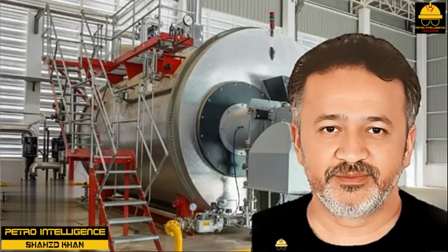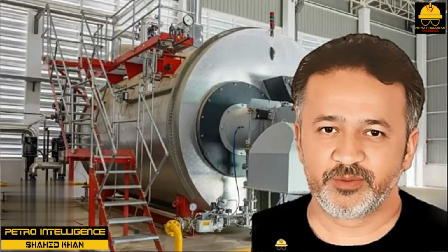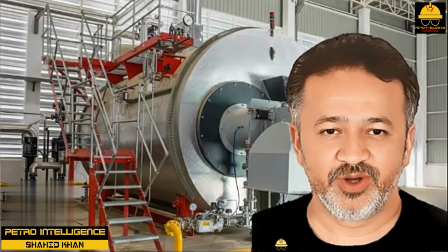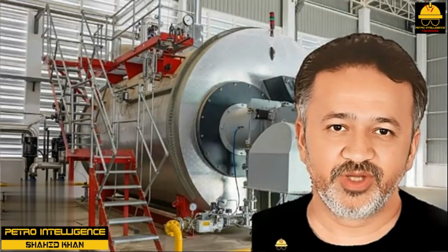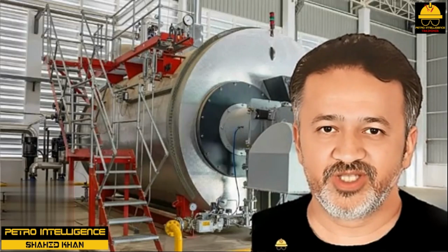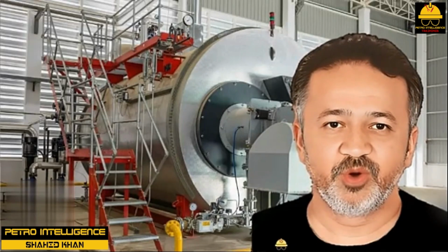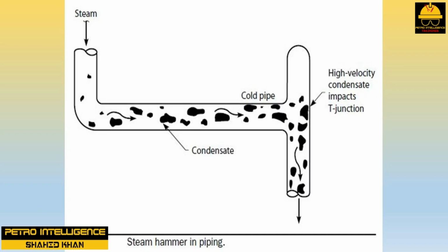Water hammer. Steam or water hammer, more properly called hydraulic hammer, is one process plant phenomenon familiar to the general public. When trying to warm up the steam system of a large amine plant in your plant, you can hear the crescendo of crashes due to steam hammer. The cause of steam hammer is illustrated in this picture. In general, hydraulic hammer is caused by the sudden conversion of the velocity of a liquid into pressure, causing a surge of pressure inside a piping system.